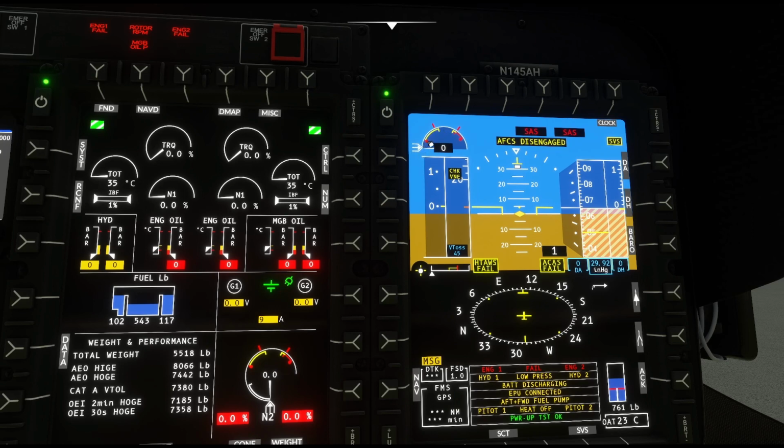All right. This is your absolute minimum transient, the low end of your minimum transient rotor speed. The transient rotor speed right inside of here is not defined anywhere that I've ever seen as to why they give you that big of an arc, but you can operate down in this area without too much trouble. So this right here should be about 96.5 if I had to guess, because 96.5 is the low end of your normal operating range.